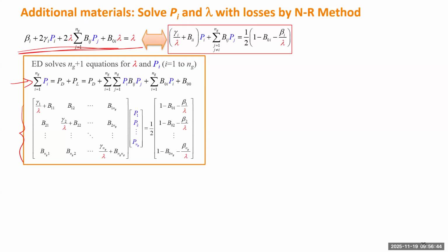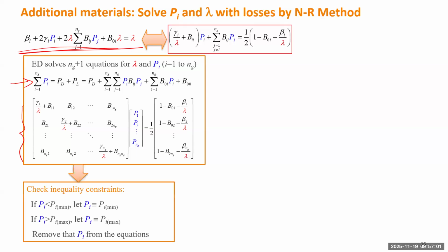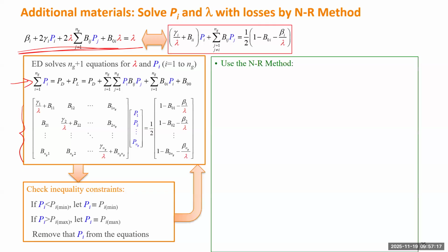So how do we solve those equations? Actually, those equations together are not more complex compared to the power flow equations. If you write down the power flow equations, power flow may be more tricky because there are sine and cosine functions, or you even consider real and imaginary parts for complex power. So for this set of equations, we want to use the Newton-Raphson approach. We want to make sure the limits are satisfied, which means during the iteration, if anyone reaches the limit, you need to stop there. Don't further change that value.